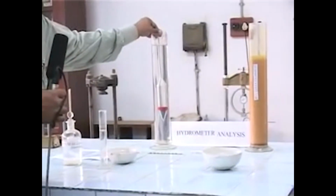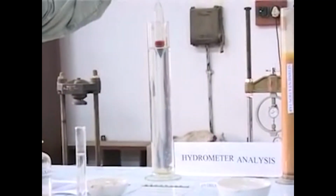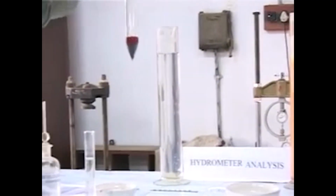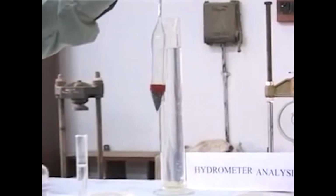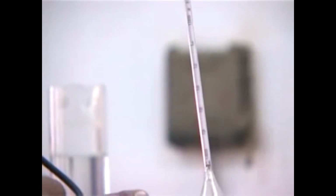Then, before the soil starts settling, we are going to place a hydrometer like this into the slurry and find out what reading we observe at a particular time on the stem of this hydrometer.